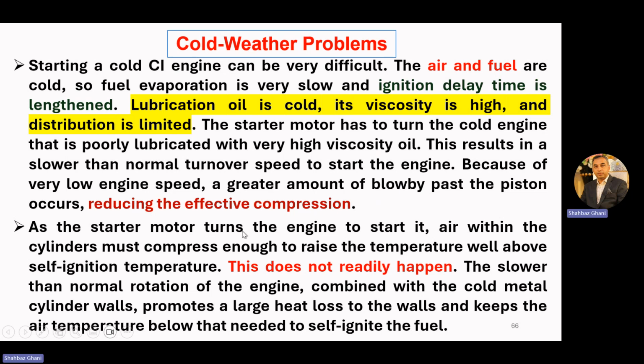As the starter motor turns the engine to start it, air within the cylinder must compress enough to raise the temperature well above self-ignition temperature. This does not readily happen. The slower than normal rotation of the engine combined with the cold metal cylinder walls promotes large heat losses to the walls and keeps the air temperature below that needed to self-ignite the fuel.